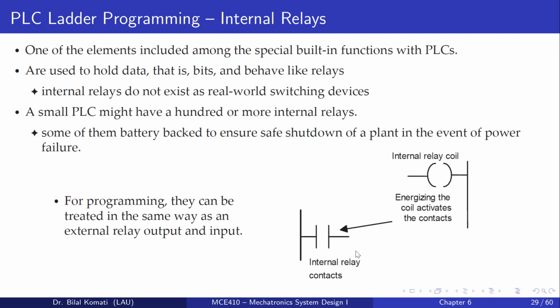So we can use them to ensure that everything is switched off, even if we have a power failure. They can be treated in the same way as external relay outputs and inputs. One PLC might have 100 or more internal relays.